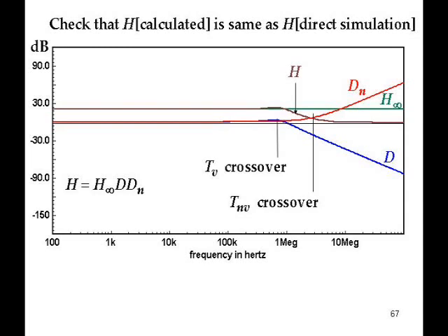Why is that? It's because the H0 term has taken over. It's the direct transmission to the output through the feedback path that is determining the output at high frequencies, even though the op-amp gain has gone to 0. So that's an important difference, which you would lose if you don't account for the direct forward transmission through the feedback path. Big difference.